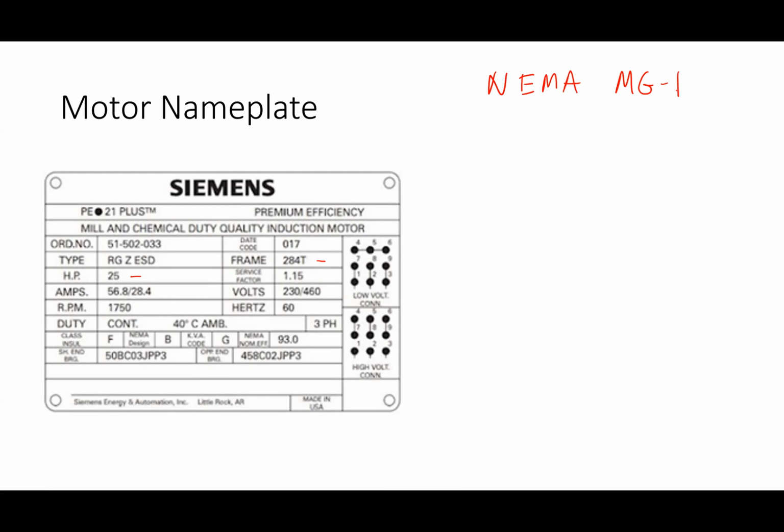Okay. In this case, what I'm looking at is a 25 horsepower motor, which is rated for 230/460 volts. All right. So something's a little bit strange. That's 460. First of all, the motor rating is always in line to line voltage. Now, 460 is a different number than I typically use, right? What number do I typically use for line to line when I give you guys problems? 480. All right. The reason they do this in NEMA MG1, they rate it at 460 volts.